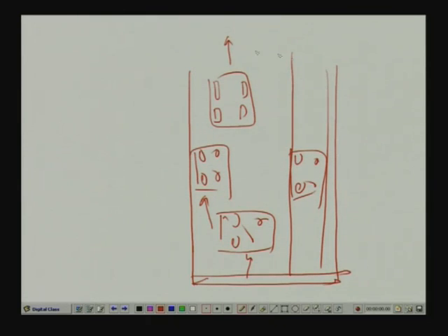So, if you put these wheel loads exactly in the same position and calculate stresses in the edge region, on the other hand, if you put only 6% of all this vehicular traffic exactly in the edge region position as shown here, in both cases the edge stresses that are computed will be almost similar.